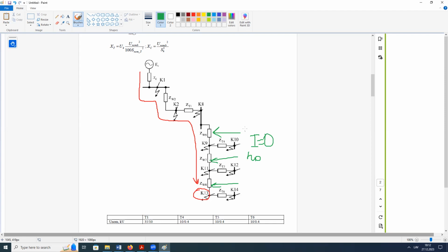You see, there is no source, only current flow from a source to the node, yeah? Voltage is zero, you know. Current flows from the higher voltage to the lower voltage, the difference in potential. In the place of a fault, in a node of the fault, the voltage is zero, the lowest possible. It means that all the currents flow to this node.